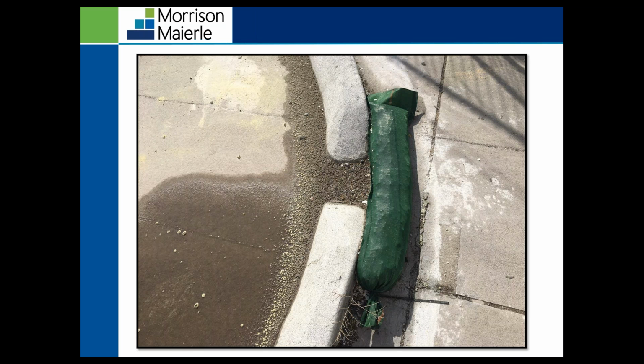You can see on the left right there, all that sediment that's trapped, and on the right there, really is minimal sediment that is discharged from the site. And this is a really good BMP to use when you're using it on asphalt or any other type of impervious surface.